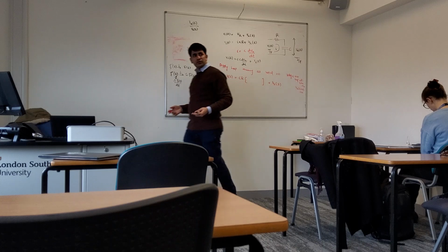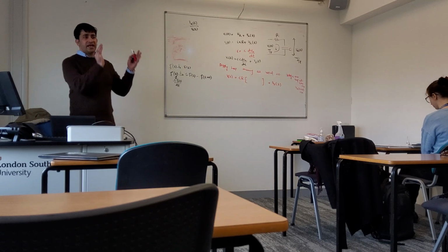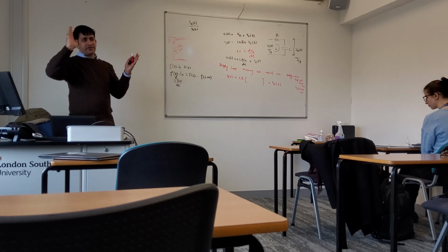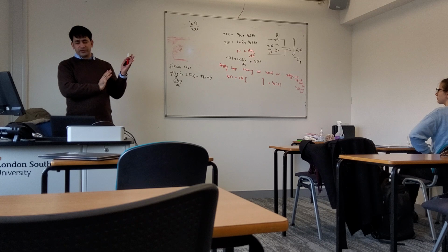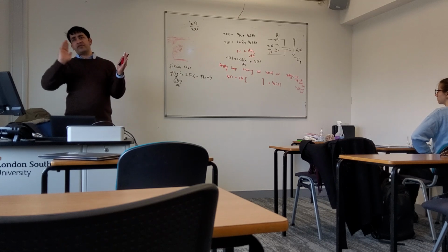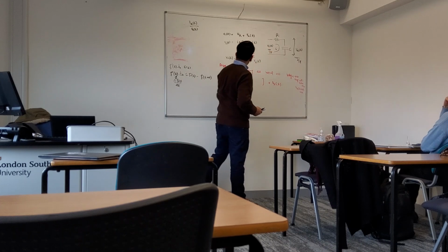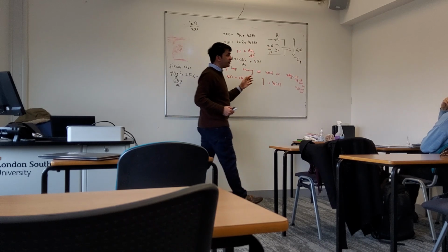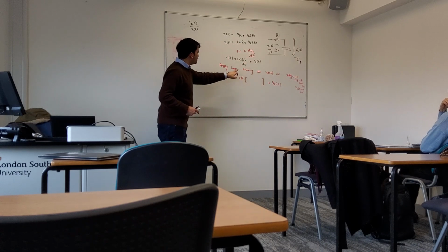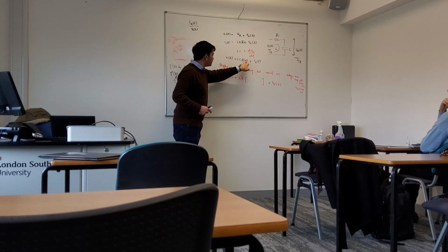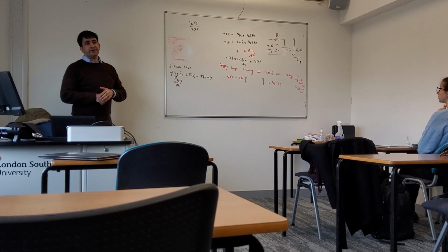I know that for V2 the Laplace transform is, like I said in the previous case, that if x of t is input and y of t is output, then in the Laplace domain it would be X of s input and Y of s output. Similarly here, V1 of t is input, so its Laplace transform is V1 of s, and V2 of t is output, so its Laplace transform is V2 of s. Now this is the transform for the derivative of V2. So what would it be?